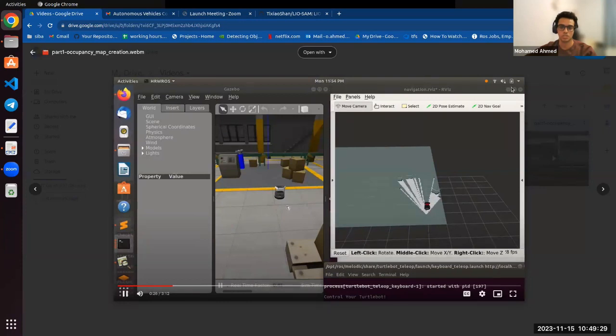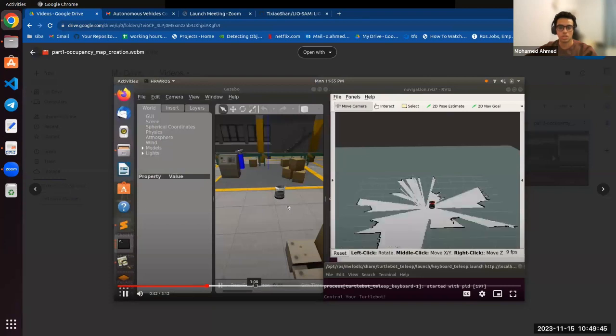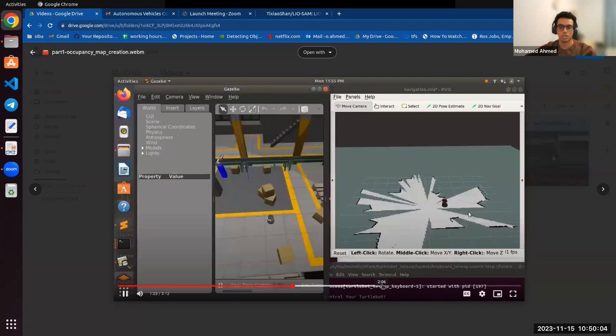This is the visualizer for ROS. And this is the simulator, it's called Gazebo. And here I was using some libraries and tools like MoveIt, C++ code, and Python and stuff like this. This was a small project that goes from one place to another. At first, the robot moves around and tries to figure out the environment around it and save this map for later, and meanwhile tries to avoid the obstacles.